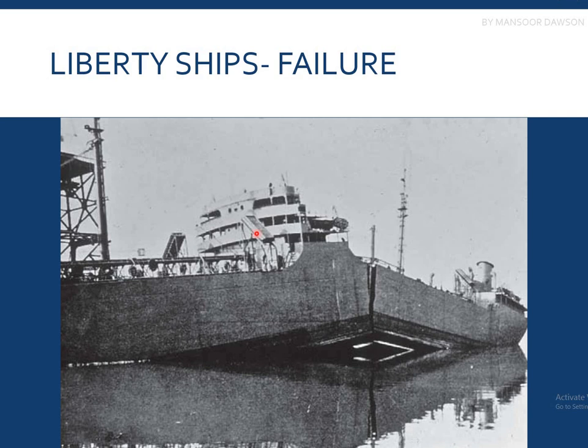So what happened was the properties of the material used for the ships were expected at room temperature, but the ships were supposed to be used at sub-zero or very low temperature. That was not actually room temperature, about 25 to 30 degrees centigrade.